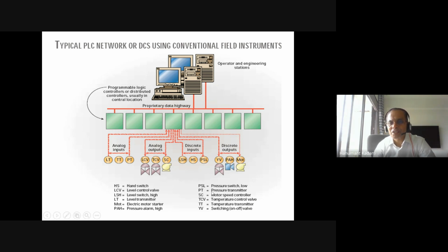You can see here PSL means pressure switch low, LSH means level switch high, LCV means level control valve. So this is the nomenclature description here.